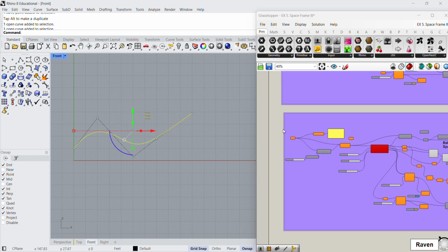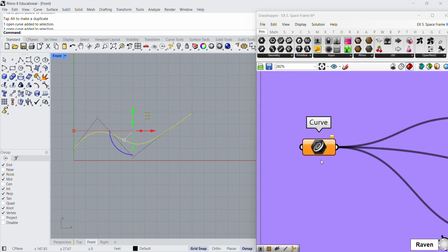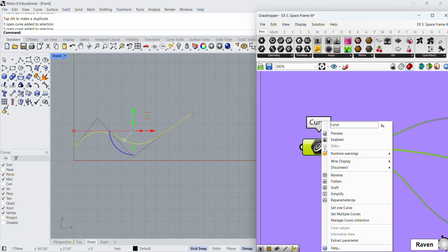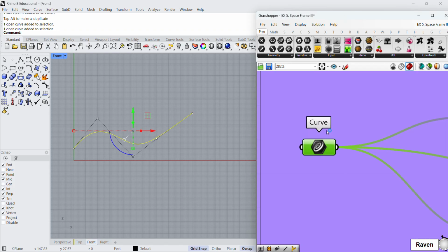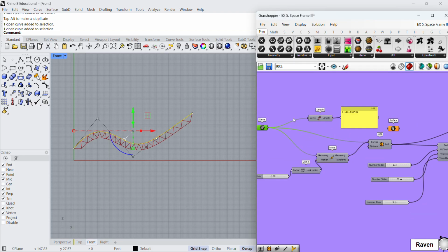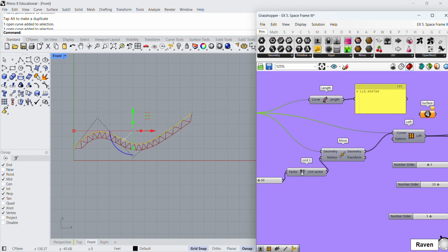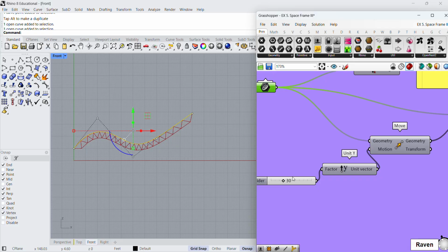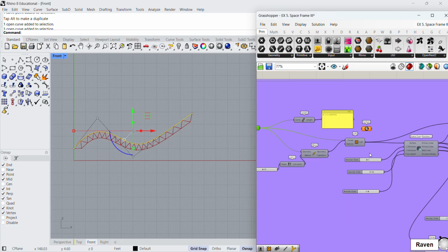So first, you need to select and dump this curve, right? So I'm gonna assign this curve to this curve command. As you can see, when you walk through that, obviously this curve is drawn on the XZ plane, but I copy the line in the Y direction, the perpendicular direction, at 30 feet spacing.